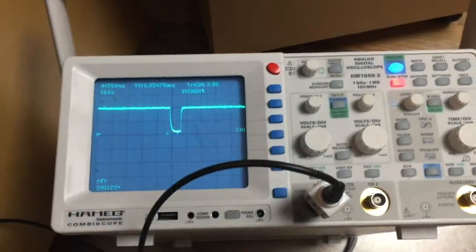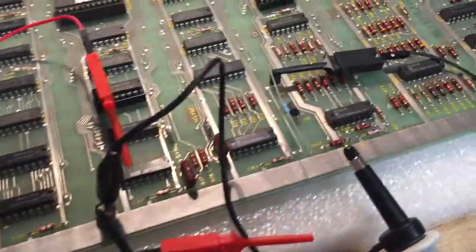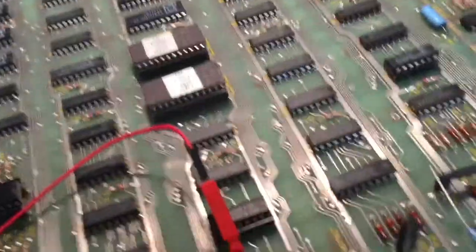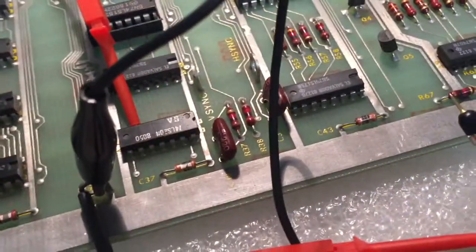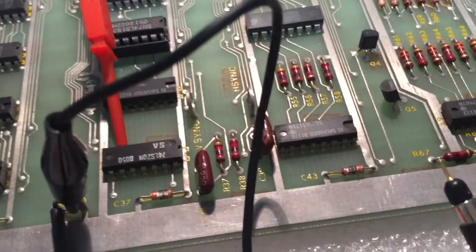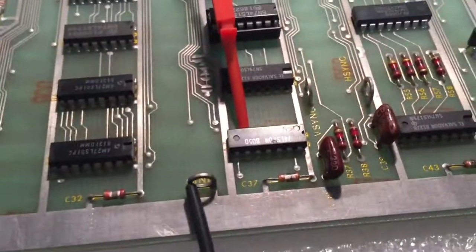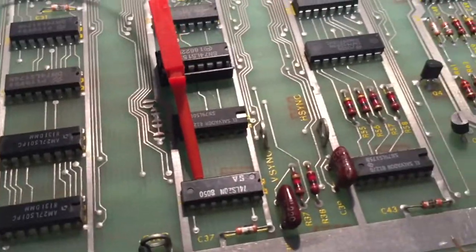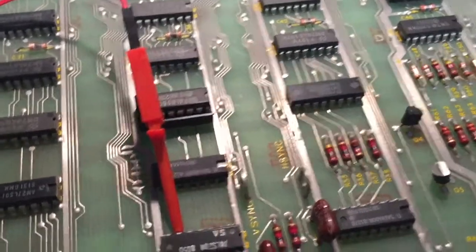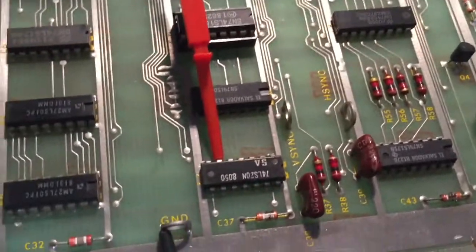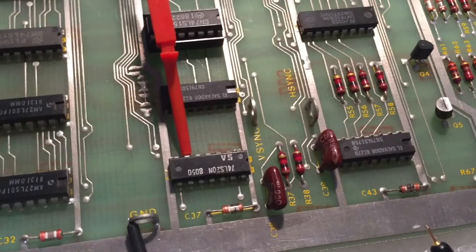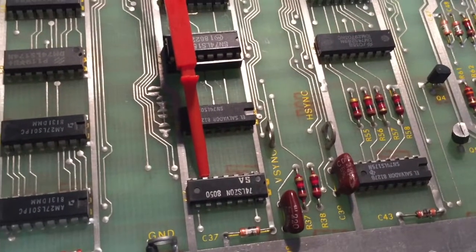So, as a permanent fix, we could connect the resistor between pin 6 of this IC and ground. We could solder it on the board, but I wouldn't really do that, because I think that this might be a dying IC that might get worse over time, and we might even lose all of our available ground level.